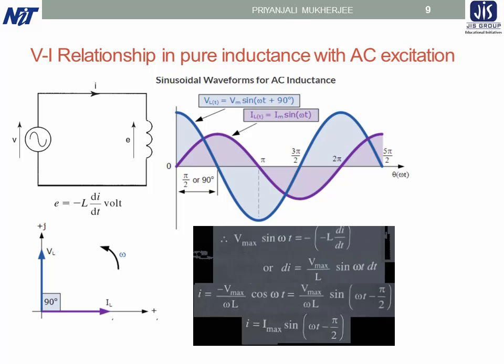Actually, inductors or choke coils are made with iron cores because large valued flux density can be produced in iron cores. So inductances of large values can be had. Air core inductors become too bulky to have an inductance of a given value.